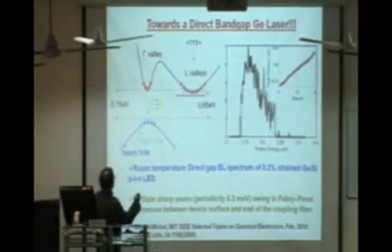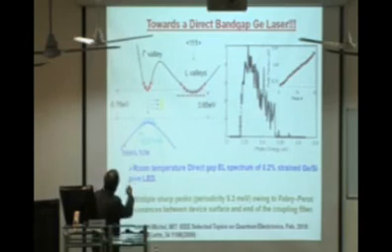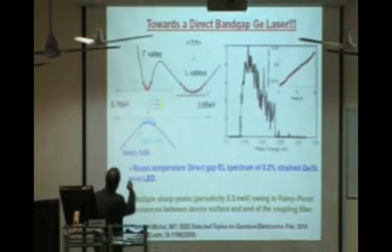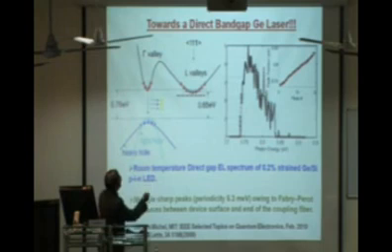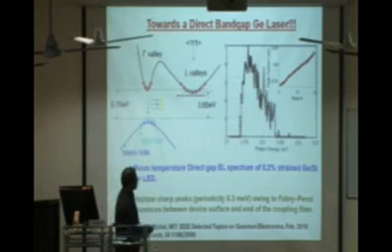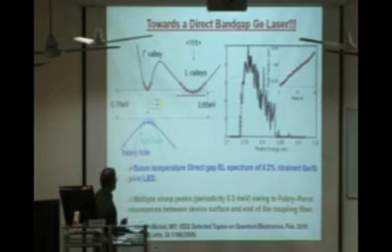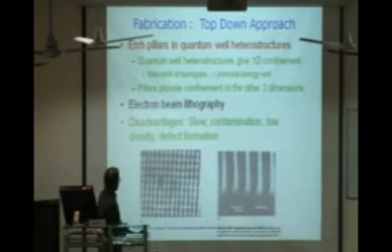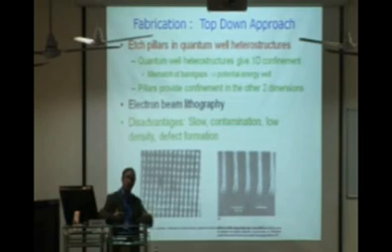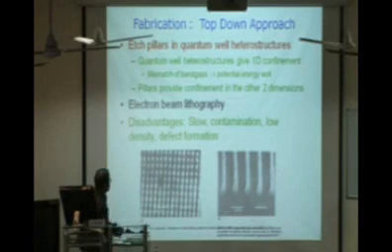They could actually populate a lot of electrons in the gamma valleys, which ultimately gives rise to radiative transition and gives rise to the so-called band gap emission in the case of an indirect bandgap semiconductor. So they claim it's possible to make a laser from this kind of structure, but of course not yet possible. The next step is whether you can make quantum dots which can be strained and have modified selection rules, so that we can get emission from them. In fact, that is possible.